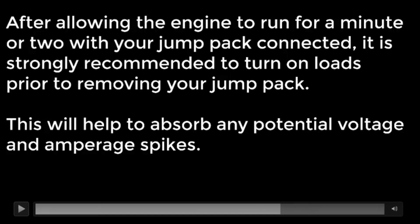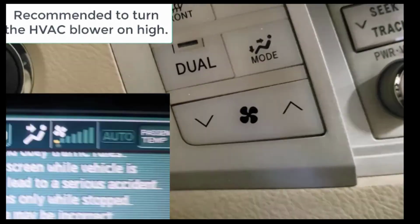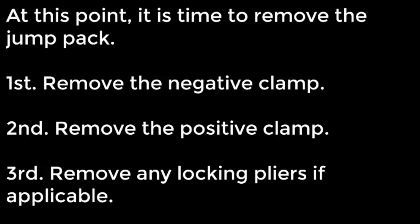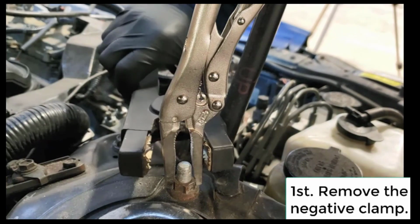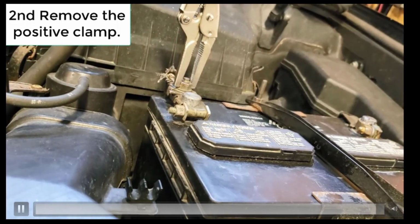And one example I'll use here in this video is I want to turn on my HVAC blower motor on high. So I'm going to crank it right up here, and I'm going to turn on rear defrost if I can. That will really excite the alternator. Then I'm going to remove my negative clamp first, my positive clamp second, and then take out any vice grips or locking pliers that I had installed to make sure I clean up my work area.